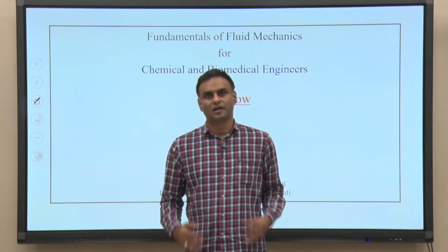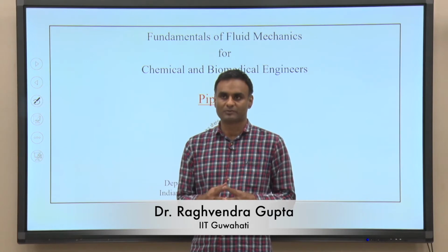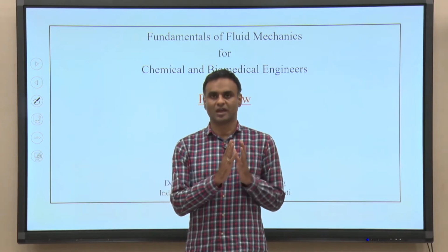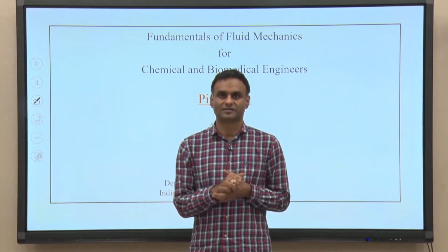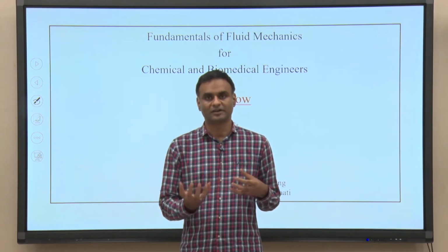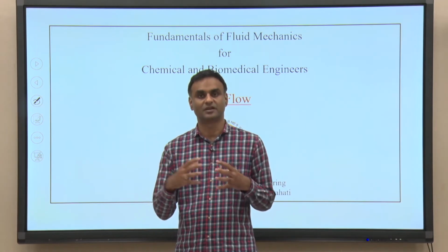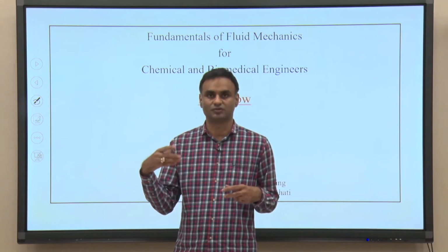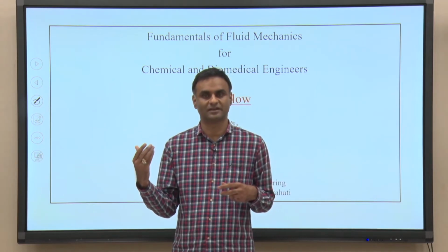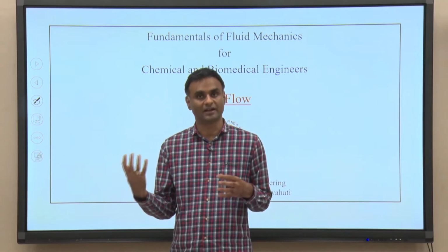Hello. In this module, we are looking at pipe flow problems, especially how we can solve them using one-dimensional equations, using Bernoulli type equations. But the difference from the Bernoulli equation is that we can take into account the frictional losses and other losses due to flow separation, etc., at different fittings, valves, inlet, exit, etc.